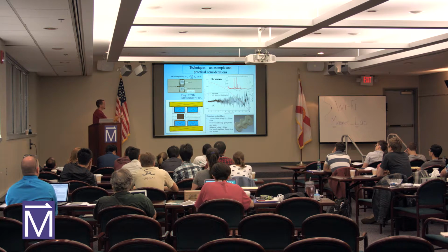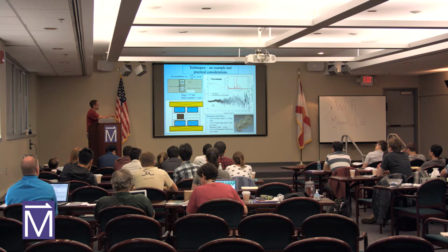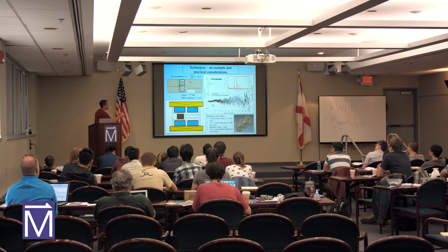So I did this measurement here in the PPMS that you guys have all visited. There was a 77 hertz frequency, 5 milliamp drive into the excitation coil. The red line here shows the data that was collected on a lock-in. As I sweep the magnetic field from 4 to 16 Tesla, you can see that it changes maybe 70 or 80 microvolts in the signal.